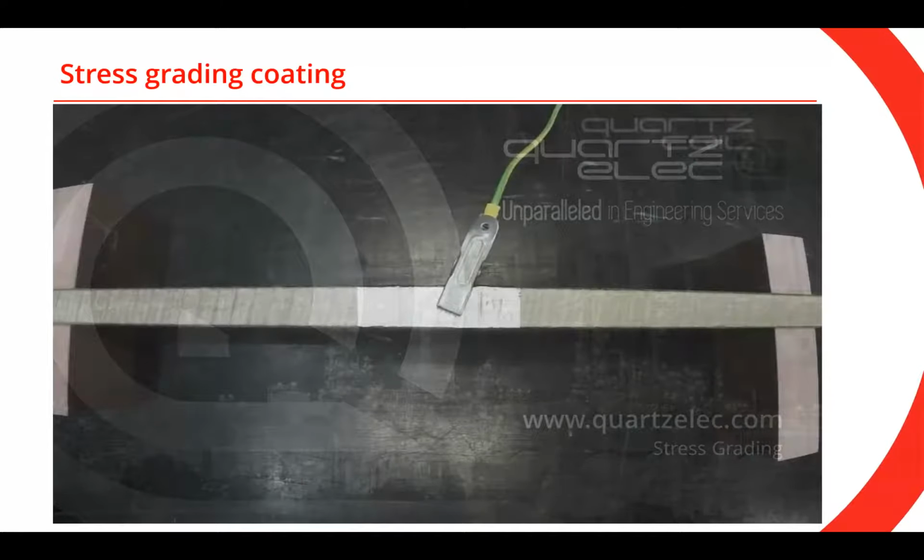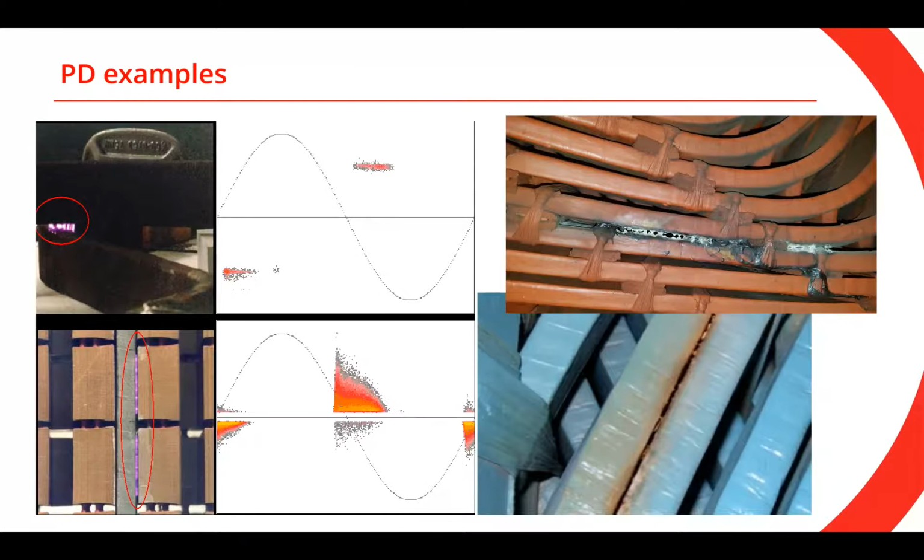All right, another good example. This is a partial discharge between two adjacent phases. This is the location where one of the stator bars will have the highest voltage potential, which is the rated voltage of your machine divided by square root of 3. And then the adjacent stator bar will have potential 0. Let me just find a pointer. You can see two examples here and there where these two stator bars suffer from partial discharge.